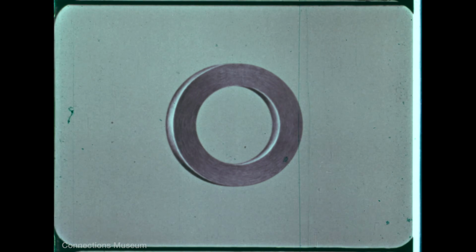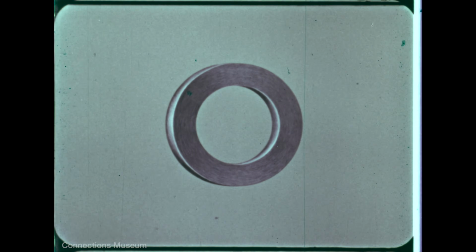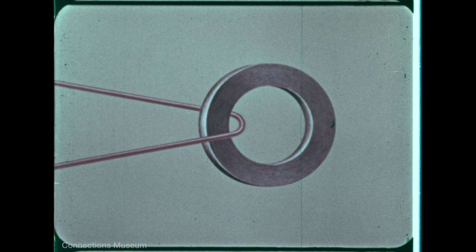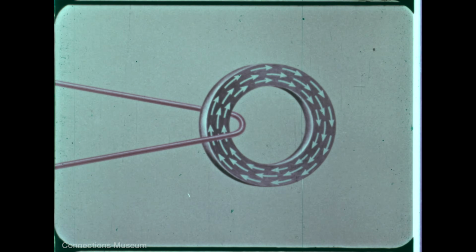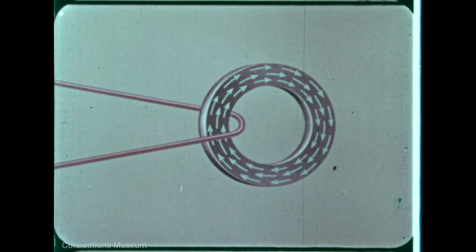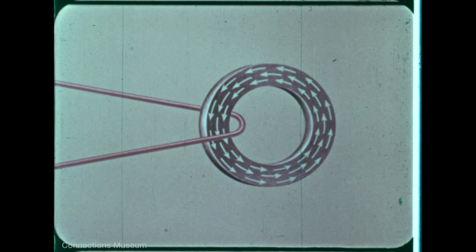The core is molded from powdered ferrite with a binder in the form of a tiny ring. It is useful as a binary memory device because it can be magnetized in either of two states. When a conductor threaded through the core is pulsed with a current, the core becomes magnetized and will remain magnetized until a pulse in the other direction reverses its magnetic state.